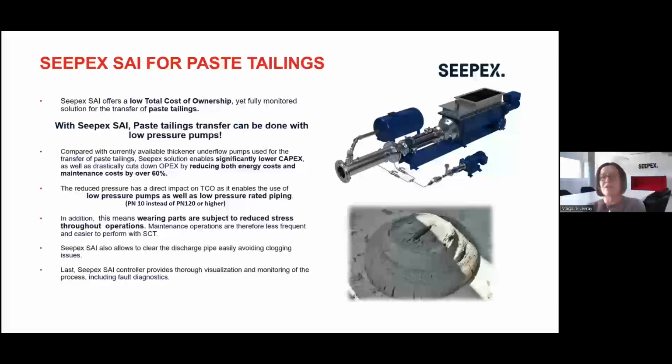Also included in the system, because we are using air injected in the discharge pipe, that brings us a ready solution to clean the discharge pipe, and thereby avoiding any issues from clogging, whether the tailings got dry in the discharge line or whether it froze and broke the discharge line.